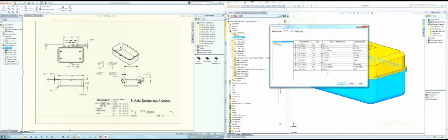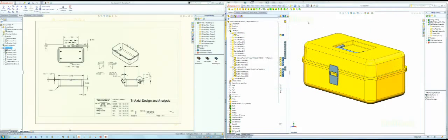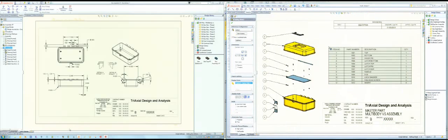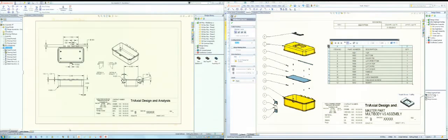And I just typed in the name. Same thing with the part number. I just assigned a cut list property called part number, and I made up part numbers for all of them. And then when we got back in the drawing, I just changed the cut list so it had a couple of extra columns in it and hid a few columns, and now we've got something that looks like a bill of materials, right?